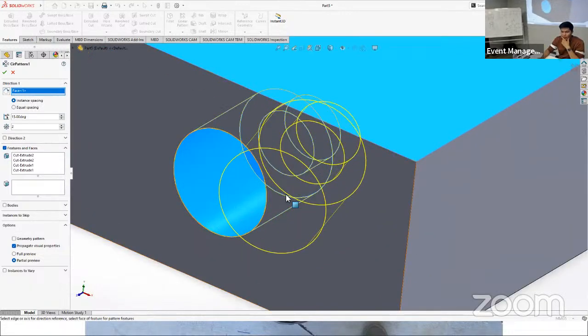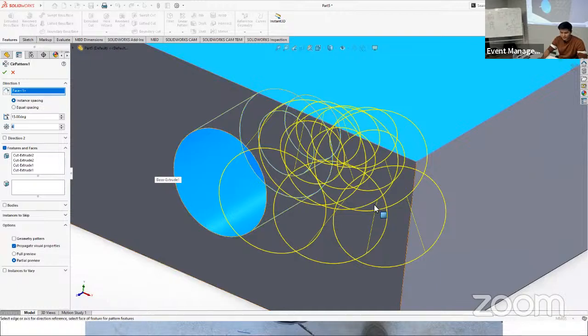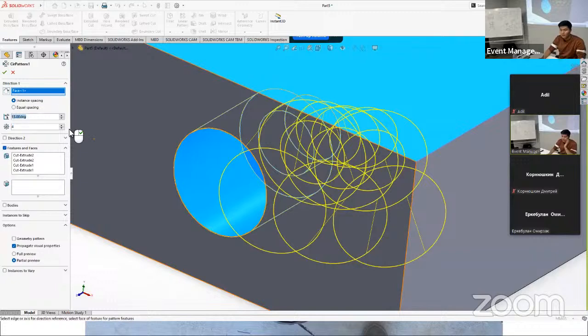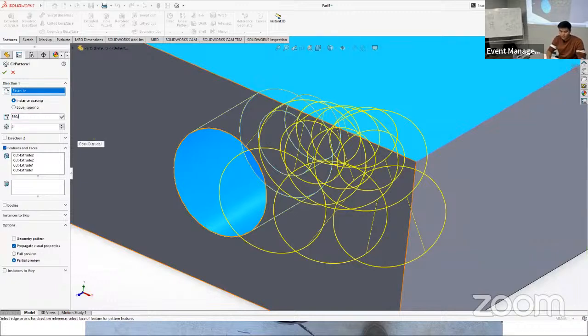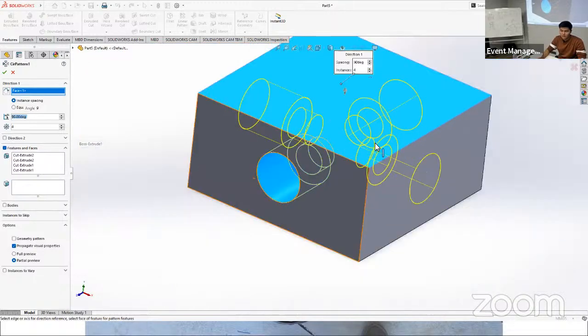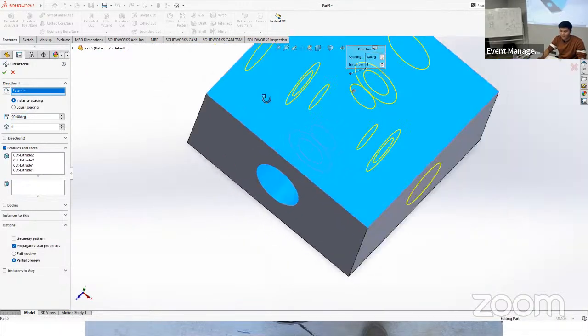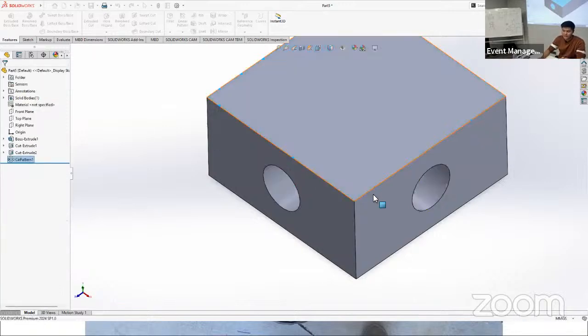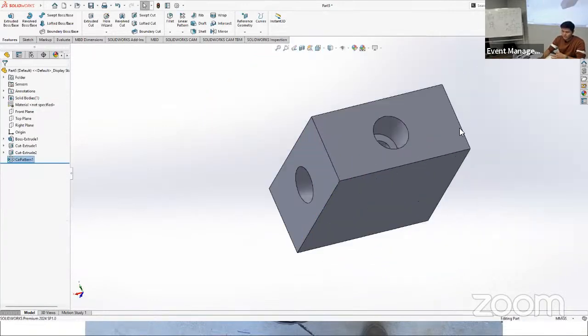And it's already showing us a preview of our second cut, but we need a total of 4. So there's the number. We're going to enter 4, but it is overlapping each other. So actually we have another parameter of angle, and since it's symmetrical around 360, we divide 360 into 4. And it's going to be like that. And if we accept that, it duplicates all the holes.